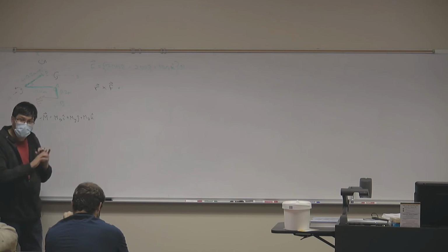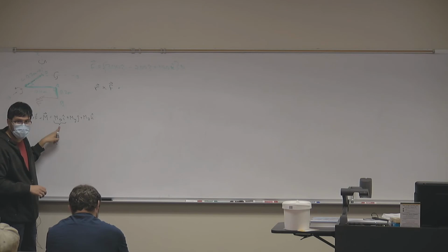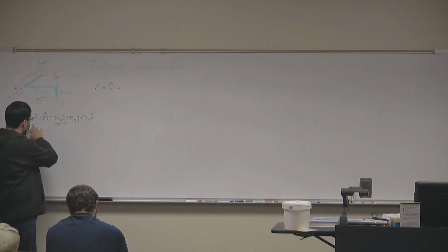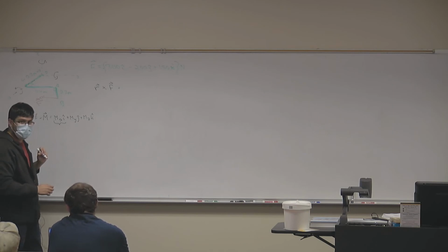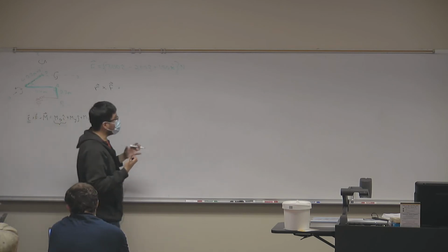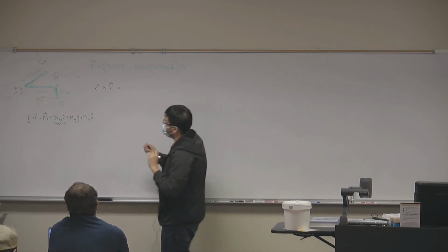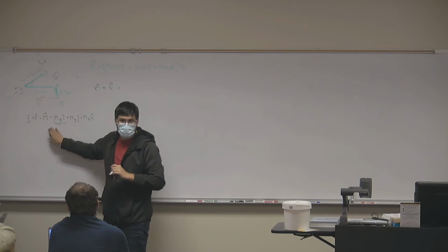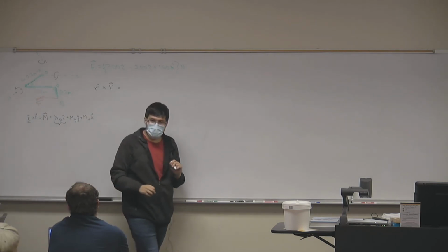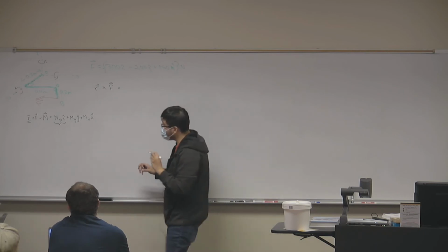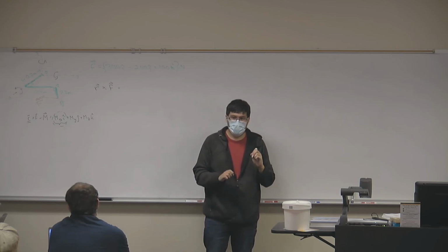So we are right in that we only need one component of this moment. But to calculate this moment, we still need the position vector that considers all of them. There are going to be easier ways, and we're going to learn them as the class progresses. But right now, I don't want you to get confused. I don't want you to think that because we only need the x-axis, our position vector somehow changes towards the x-axis. The position vector is not what's going to change. What's going to change is the component of the moment that we select in the end.